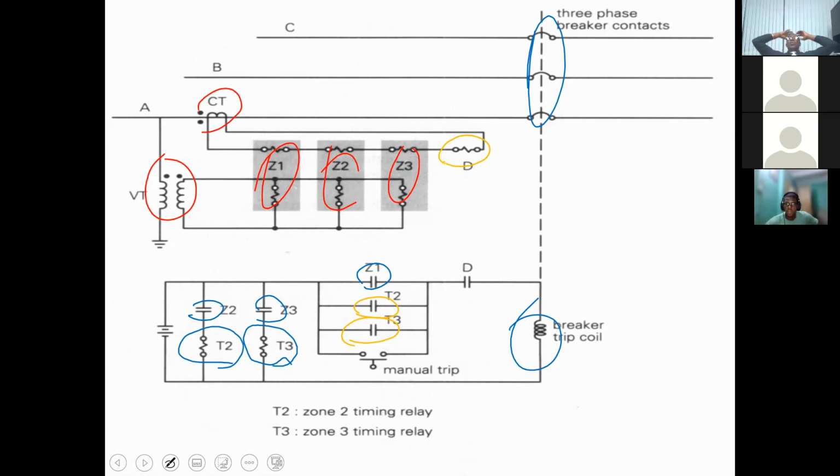One of the things you need to bear in mind: at your substation, you must have a constant supply of electrical energy, and it is supplied by batteries. So you use a station battery. You don't rely on the utility, except in as far as you require it to maintain a charge on the batteries. You with me? Yes. So you always have a station battery and you'll always see a DC source there.